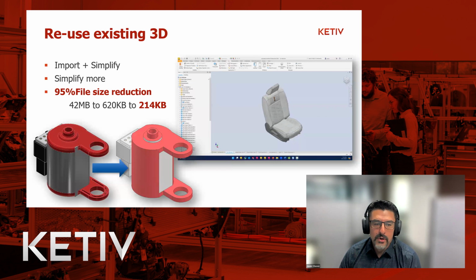You can see an example of this motor. In the example that I'm going to show you, and we're going to be flying through this, we got a 95% file reduction, right? We took out internal little details. We went from 42 megabytes to 214 kilobytes in the end, right? To see a major improvement in performance. And that's not just in this current design, but in the future, if anybody uses it from our library, they'll see the same thing. So don't shoot yourself in the foot. Make sure you process these files so that they're lightweight and usable in the future. So let's go ahead and begin here.